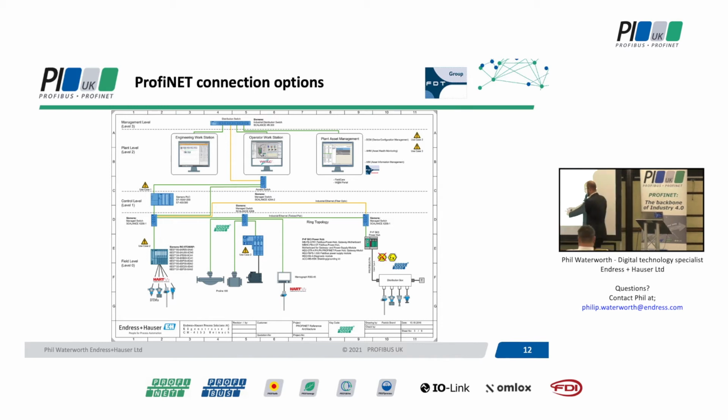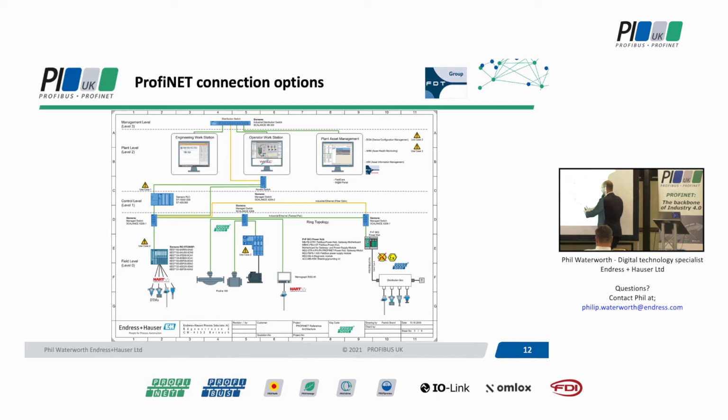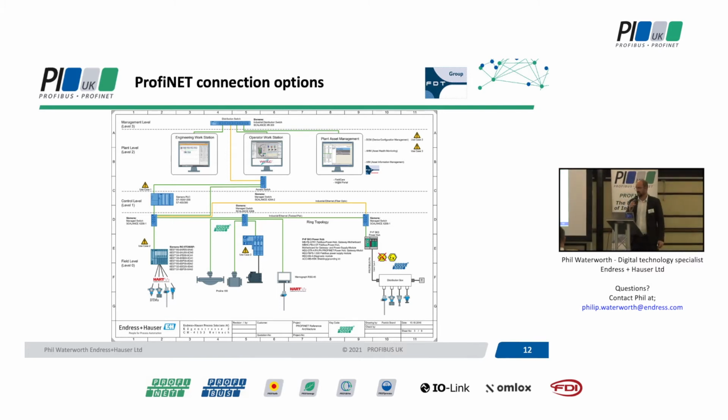And the devices at the bottom on the different protocols, Profibus, PROFINET, HART, etc., IO-Link, I guess, as well in some situations these days, will all have device-specific drivers. Put them into the software, you can communicate with all of that equipment and extract the settings and set them up. So again, one tool, configuration of everything. No longer do we have 3 million bits of different proprietary software we need to store somewhere.